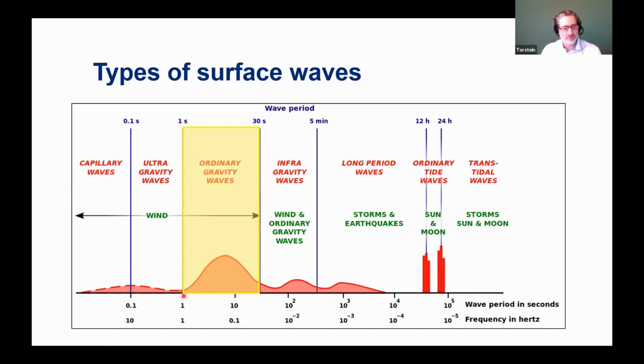You'll see that there's a bump here that shows the energy distribution that you might expect. And what we try to do when we're measuring waves is we're trying to capture as much of this bump as possible. So if you're cutting short, for instance, the short waves or the long waves, then you're not really representing the full wave field. So you could be risking underestimating the wave heights, for instance. So keep this in mind because I'm going to be actually referring to this later in the presentation.